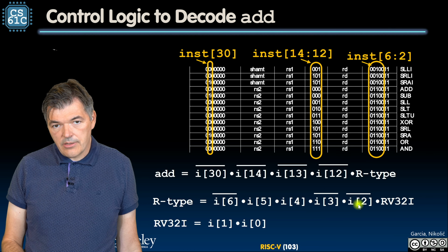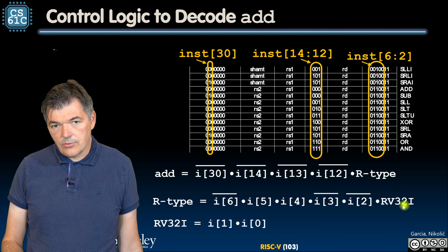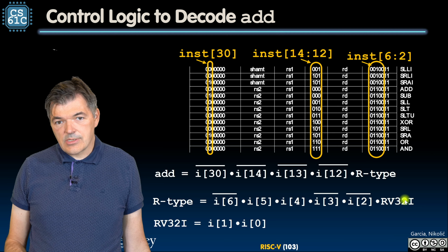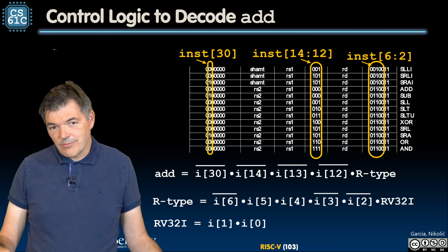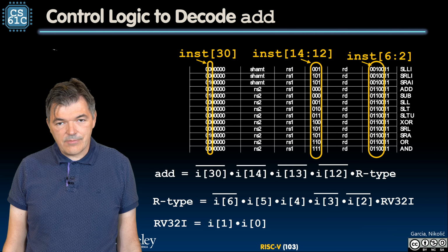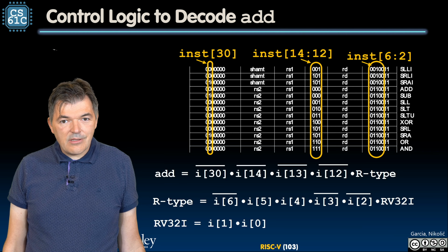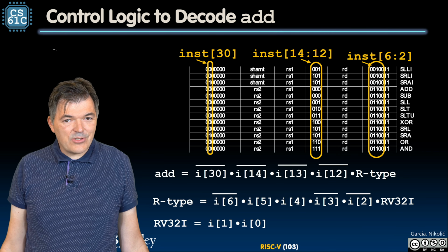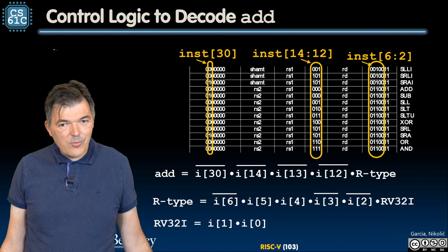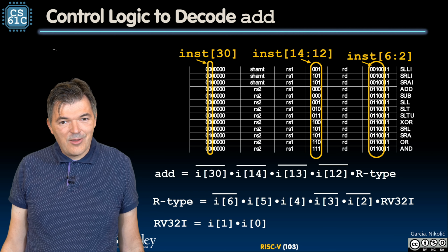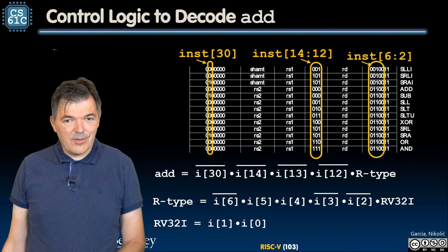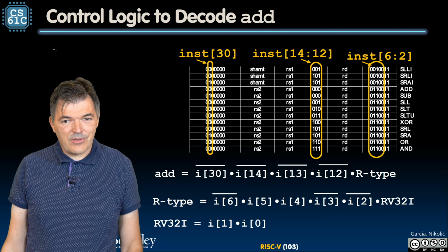If we are adding other extensions, we would have to AND this with 1, 1 in the last bit positions, but we don't have to for the purpose of our project because we don't have any other instructions. And that's it. We've just finished all what we need to know about instruction decoding. And we've done more than that. We actually built a complete RISC-V processor. We should celebrate that, which we'll do after a bit of a break.